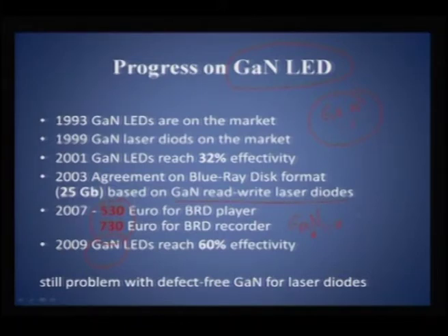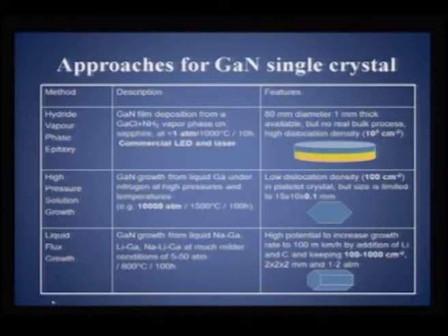The nitrogen composition will be very critical to control, and as a result it can induce a lot of defects in your gallium nitride diodes. So the flux method can give you a very refined growth, and as you see here, this is a comparative slide which tells you how important the flux growth method can be.